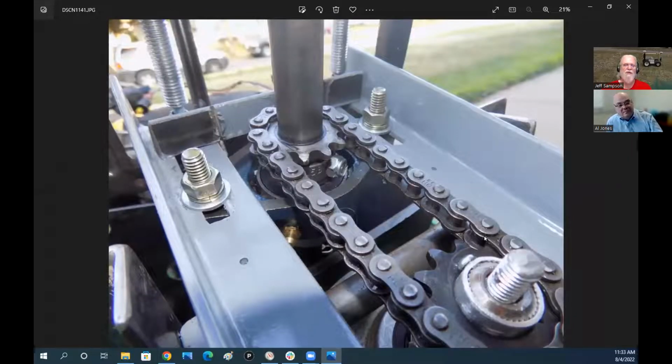And then again, this is just a close up of the motor shaft, and it's got a sprocket, and it's pinned onto it with a 1/4-20 bolt all the way through. And then here's the steering shaft, and the identical sprocket, and then I've got an M6 bolt drilled through to pin that on. And it was interesting, because I drilled the hole in the sprocket, and that seemed to work really well. I did that in the house on the drill press.